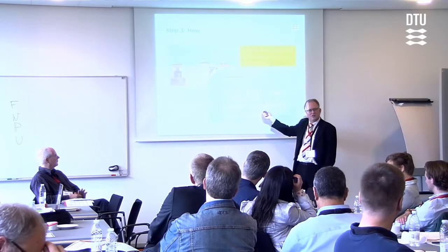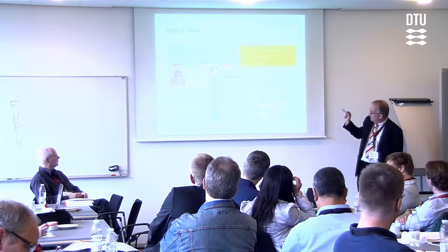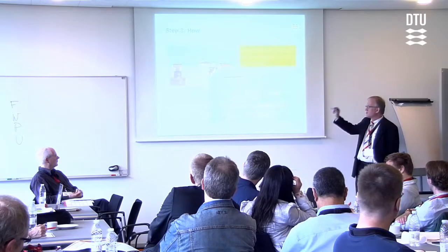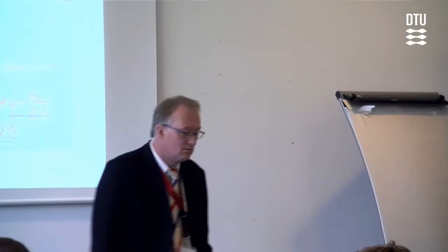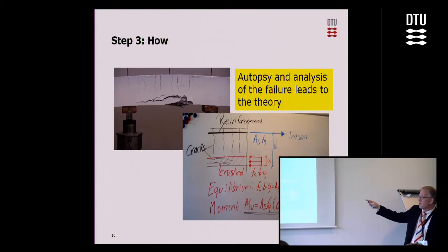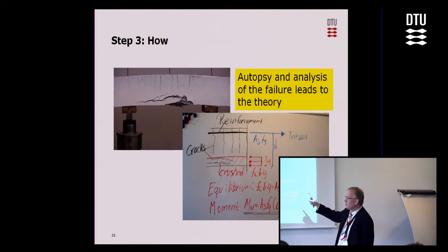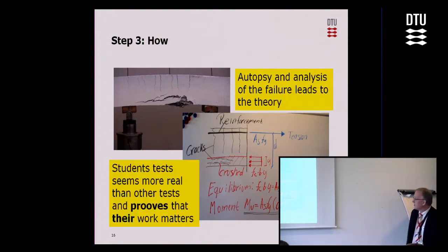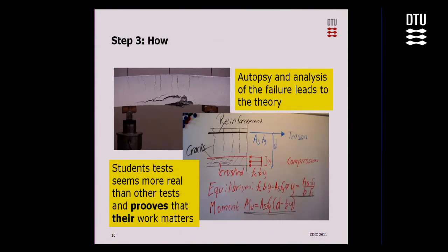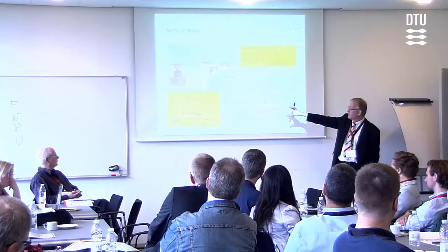And you know what? This simple formula is what is used for at least 98% of all concrete beams to design them in bending. And you have derived that just by looking at the video and using your common sense. I was a little afraid the first time I used this because I had only one reason to use that test and that video. That was, I just didn't have the resources and the time to do the testing myself and hire a professional photographer. Turns out the students actually like it. They feel such things are very real, much better than computer simulations. And we have kept mathematics on the lowest possible level until they have understood the basic things.